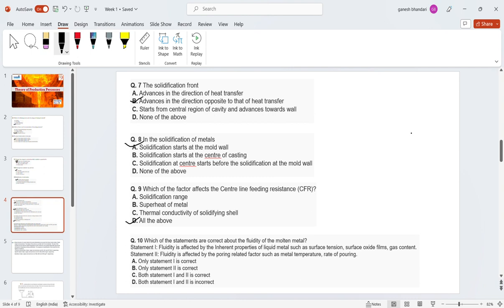Fluidity is basically calculated using some spiral test. ASTM standards are made, and it is a spiral kind of thing. At the top of your spiral you put a fixed amount, like 1 gram or 5 gram, I don't remember the standard but I know the procedure. So you just pour some fixed amount of powder in it.